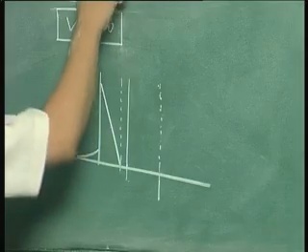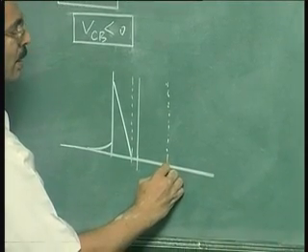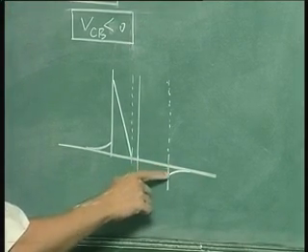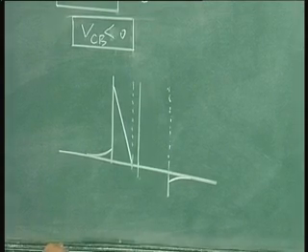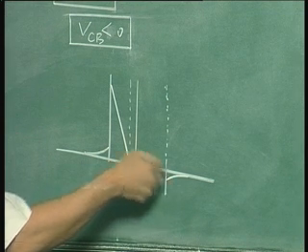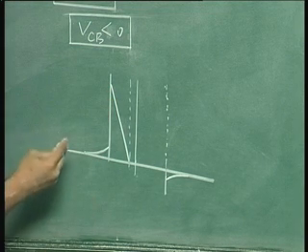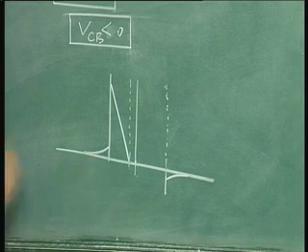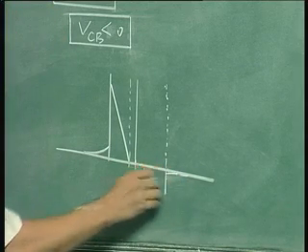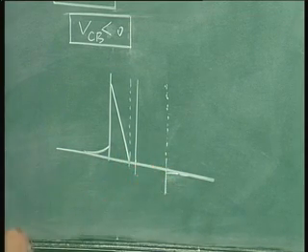Now here once you reverse bias the collector base junction, and if the reverse bias is more than 3 times Vt, then we know that excess carrier concentration here would be equal to the negative of the minority carrier concentration. So it would be something like this. This is what is responsible for the current ICO. Now if you draw this diagram to scale, then minority carrier concentration is very small compared to the concentration when there is a forward bias present, because when there is a forward bias, you know that minority carrier concentration is multiplied by exponential of the forward bias by Vt. So when you draw it to scale, in fact you will not be able to show this at all. Okay? So therefore the concentrations of minority carriers in the collector cannot be shown if you draw the diagram to scale.